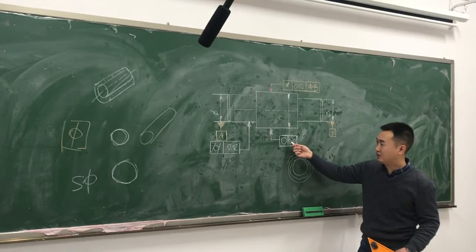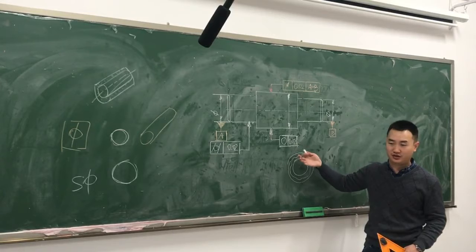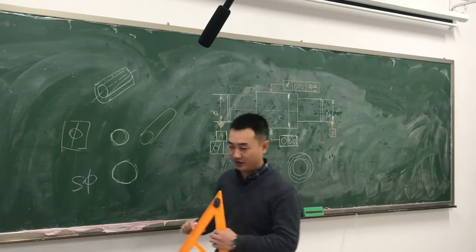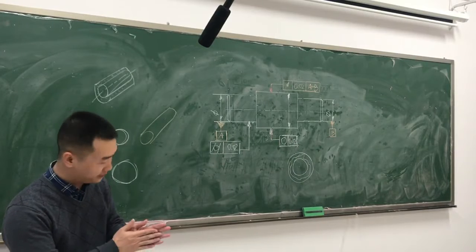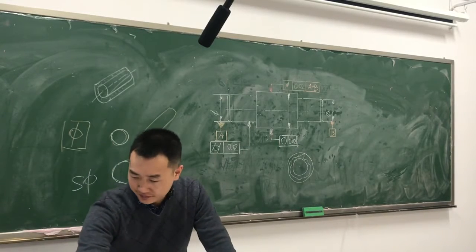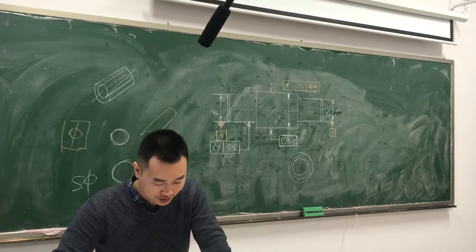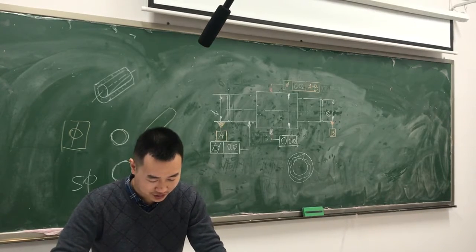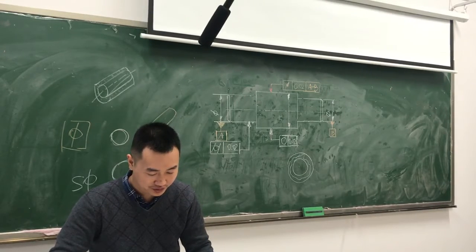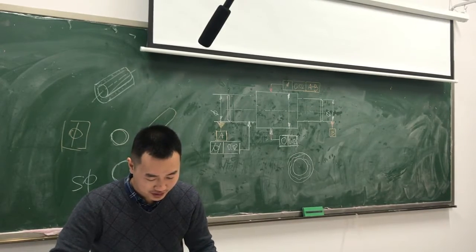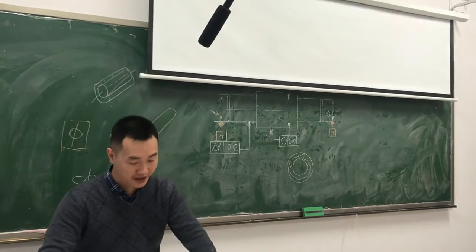So no phi should be put here before the tolerance value. So I hope you guys understand it. And we will have 2 more practices during the lesson to help you know how to label geometric tolerance better.